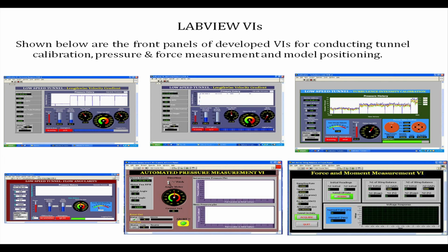So, I do not know whether a VI can be developed where you can even track such things, that somebody is getting into a danger zone. So, stop him from doing that. You give an alarm, you may be having a proximity switch somewhere looped into your VI, and that VI signals, and automatically an alarm goes, and you know that there is something going wrong.